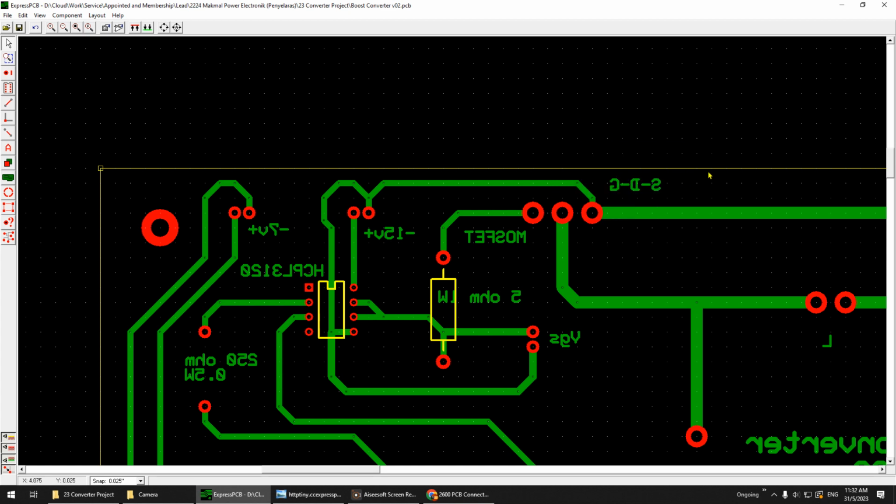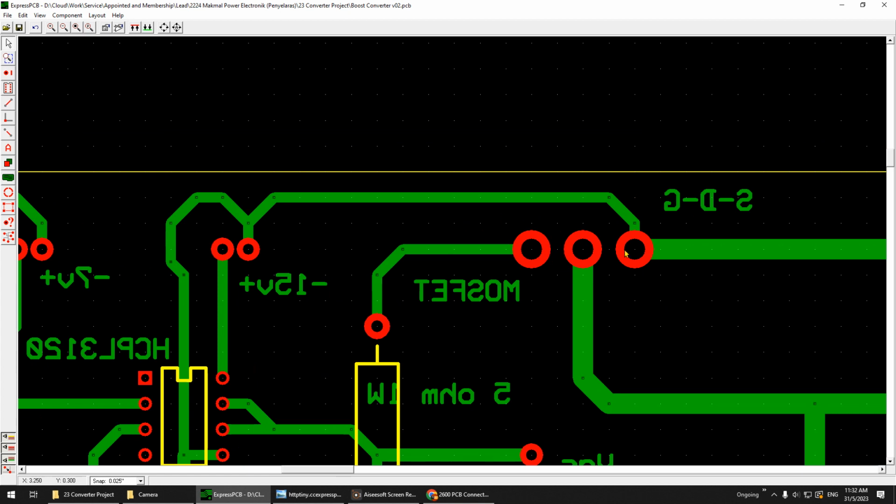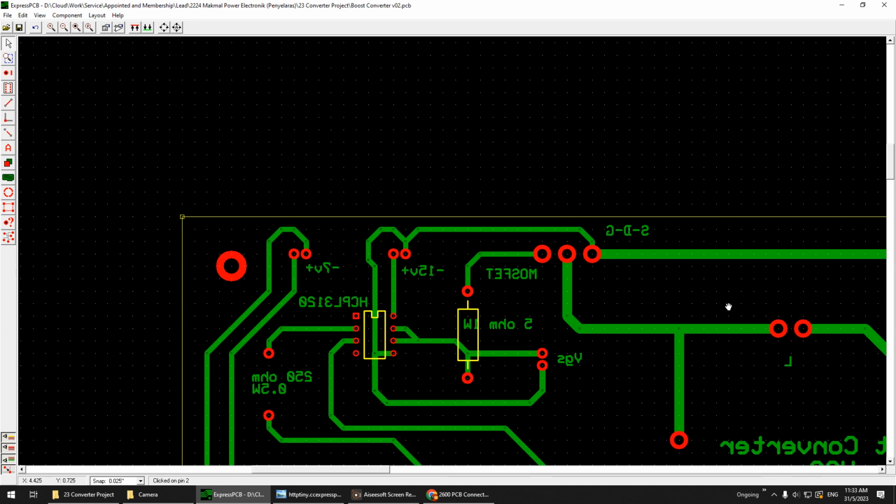The problem when I design the power electronic is that when the MOSFET runs, this is G, this is D and S, gate, and for the gate and drain usually there will be spark. I don't know why, but there are sparks. So you need to add distance. That's why I use manual pad instead of using the component itself. You can see back here, the distance is only 1, this one and this one. If manual, it will become 2. And I have to expand the MOSFET leg to make sure the distance increases. This is just for safety. Usually there is a spark between G and D. I don't know why.